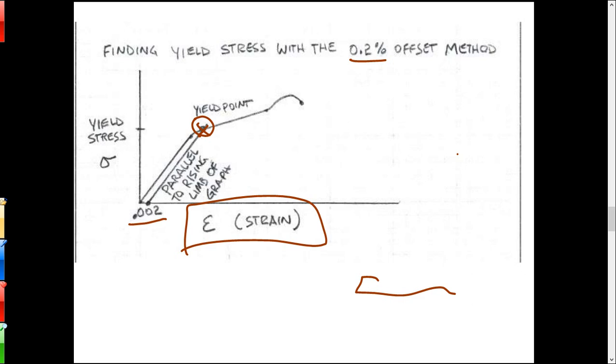Okay. And keep in mind, actual data is not this pretty. I made this graph nice and clean so you can see the different things, but real data is not that clean by any stretch. Also keep in mind that even today, if you're designing a structure, you use about a 40% safety factor. So if you think the thing has to bear 1,000 pounds, you design it so it can handle 1,400 pounds. We throw a lot of safety factors into structural work for these very reasons. We can't perfectly model all this stuff, and we want to be darn sure it doesn't break.